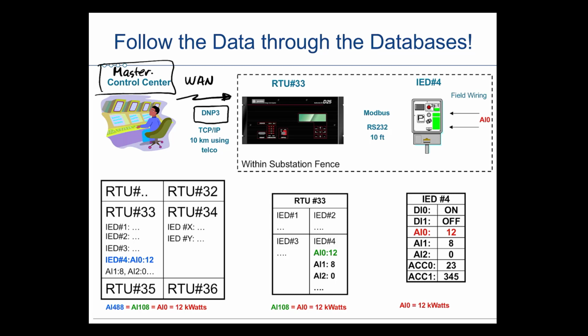It says we were operating it within the TCP/IP packet protocol, and it's saying it's 10 kilometers. So we're definitely employing datacom, which would look like an Ethernet connection to this remote, and this remote has taken on a unique identity within the network of RTU number 33.